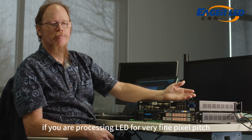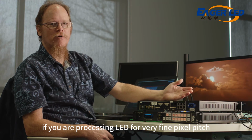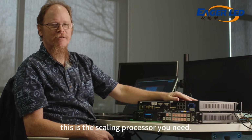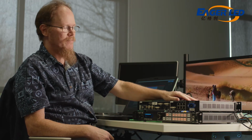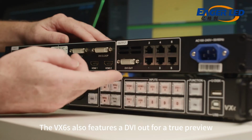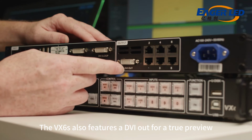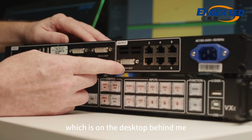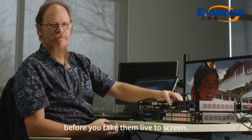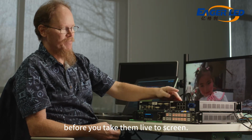If you are processing LED for very fine pixel pitch, 2.5 or smaller, this is the scaling processor you need. The VX6S also features a DVI out for a true preview, which is on the desktop behind me. All of your presets show up in preview before you take them live to screen.